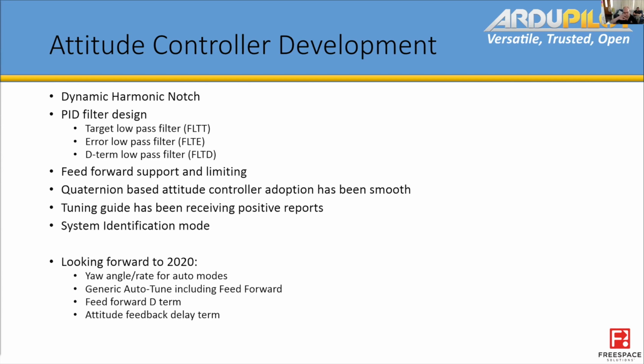So if you flip your aircraft and it comes out, we actually shut down yaw and focus purely on rotating our thrust vector until we get our thrust vector back to within a window. There's no point worrying about what direction you're facing if you're upside down. So get your thrust vector right, and then focus on your heading.